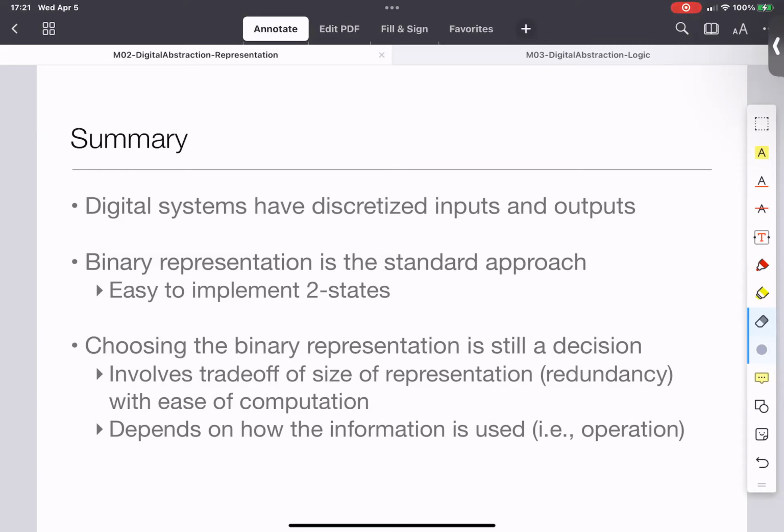And actually also generally, as we have been scaling technologies to tinier sizes, the voltages are going down. The reason they go down is because if you keep the voltage same and shrink the size of the transistor, then electric field goes up, right? Electric field is voltage divided by distance. And if electric field goes up, then my transistors are getting intuitively stressed more, right? They're being subjected to a higher electric field. So usually as transistors have been shrinking, so has the voltage been to keep the electric field constant. And so now that forces noise margin to be smaller. So there's a complicated trade-off that therefore results from that. Yeah. Okay. Thank you.